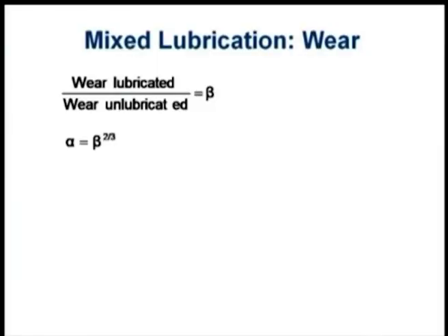In the previous slide we have shown the friction calculation and how we can go ahead with this kind of calculation. That is another way to get comparative results. But we are talking about wear under lubrication, where a lubricant is available and wear is still happening. That will cause lesser wear compared to unlubricated, because more and more rolling action will occur, and in that situation abrasion and wear will decrease.